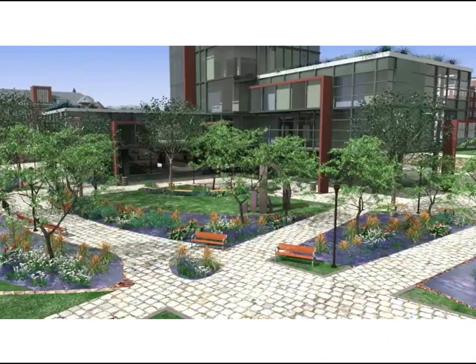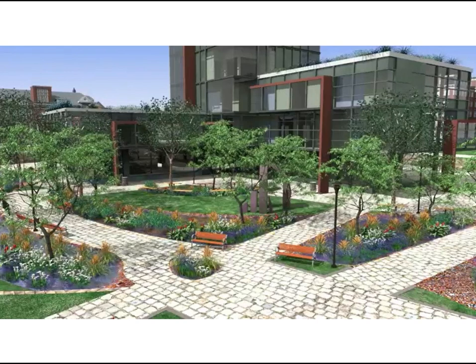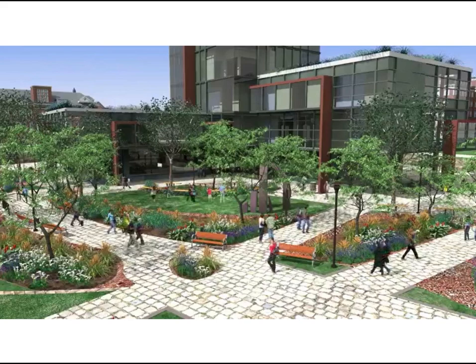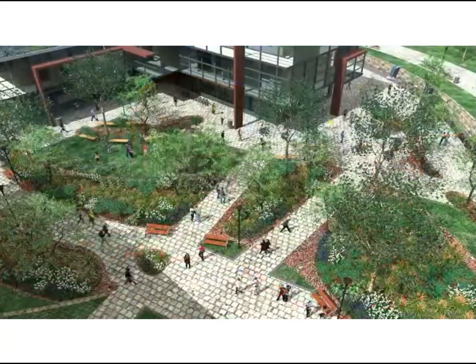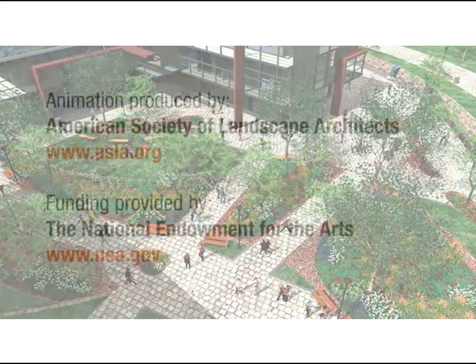As part of its function, the rain garden slowly releases rainwater into the aquifer over a 24-hour period. Just as important, the vegetation acts as a natural water purifier, absorbing pollutants and toxins from the water. Water is in high demand and shortages are common. These three systems are able to capture and treat more water than typical stormwater mechanisms. The systems are effective, easy to implement, and contribute to a more sustainable water management practice.